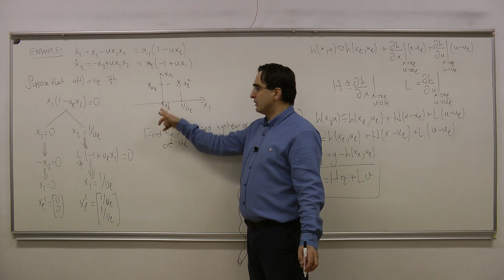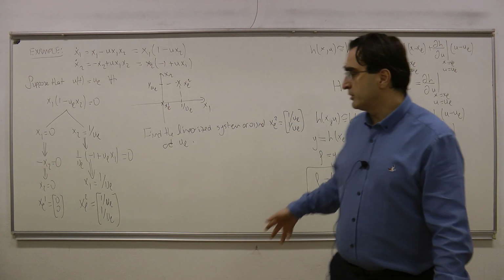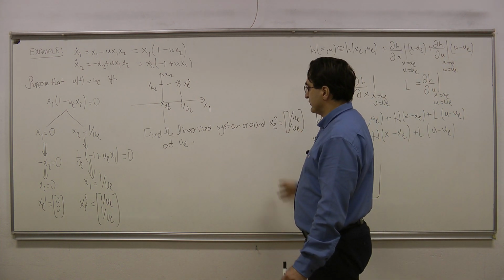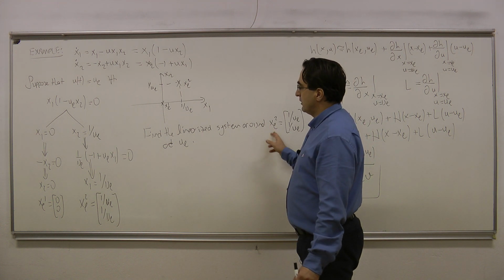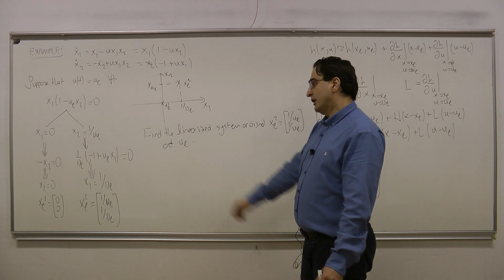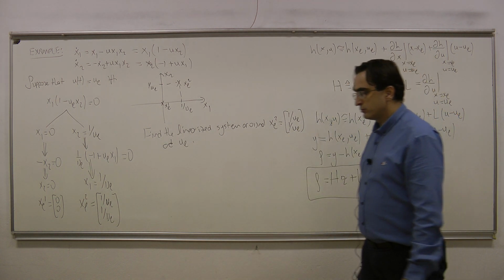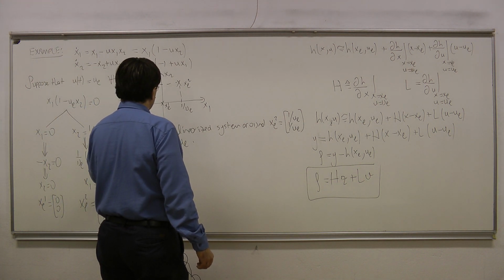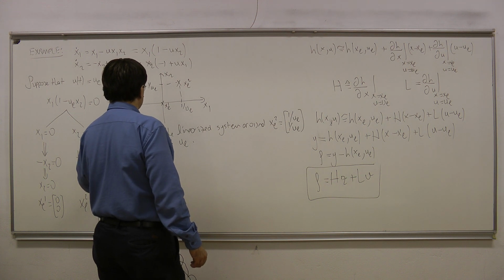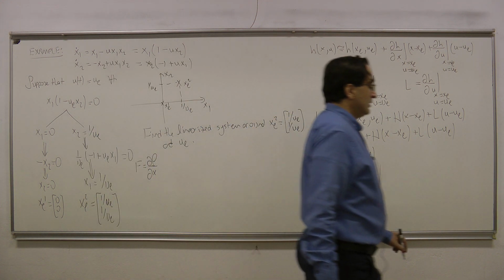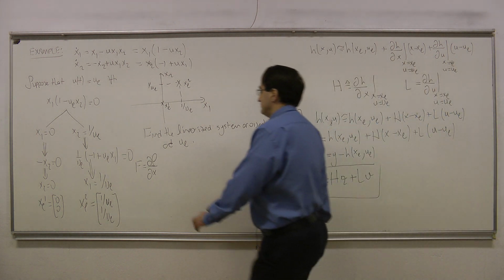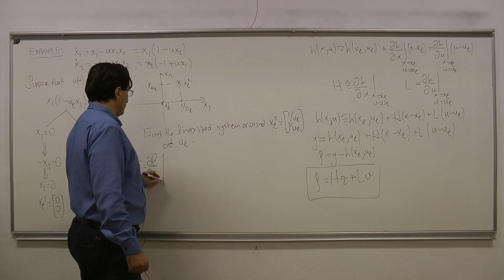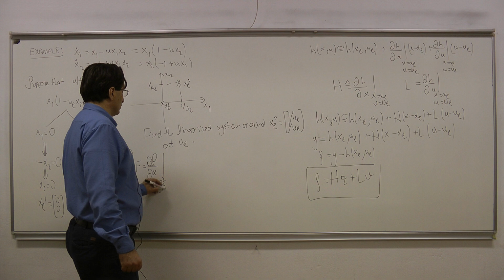Remember, the first equilibrium point at the origin corresponds to total extinction for both species here. So the second equilibrium point is much more interesting. So I'm going to linearize the system around the second equilibrium point. Just try to do it yourself for the first equilibrium point. So the first thing that I'm going to do is to calculate these Jacobians. Del f over del x, which we called the constant matrix F, and I will evaluate this at x equals to xe2, and u equals to ue.